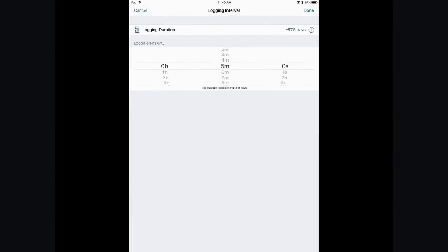So you pay a penalty for logging faster than 5 minutes because basically our battery life is based on a 5-minute or a longer logging interval, and that was based on some significant market research with some of our customers where they said 10 minutes, 15-minute logging for indoor air quality is fine. So again, this helps us maintain that 6-month battery life on the logger.